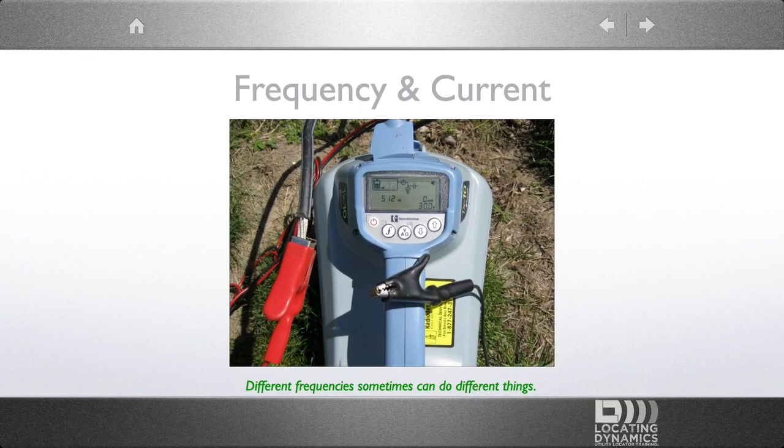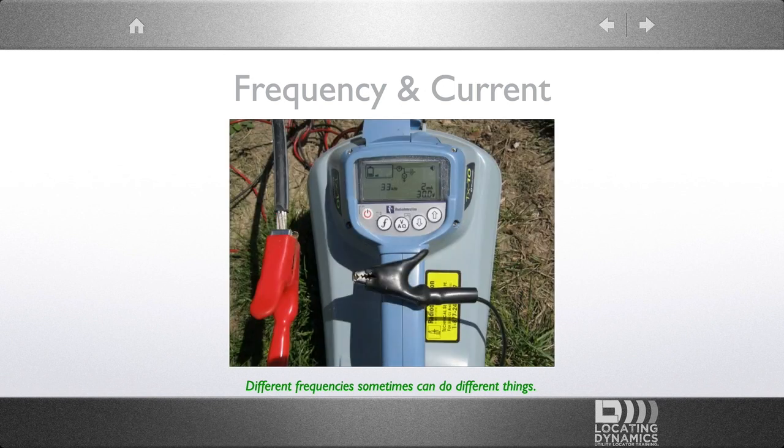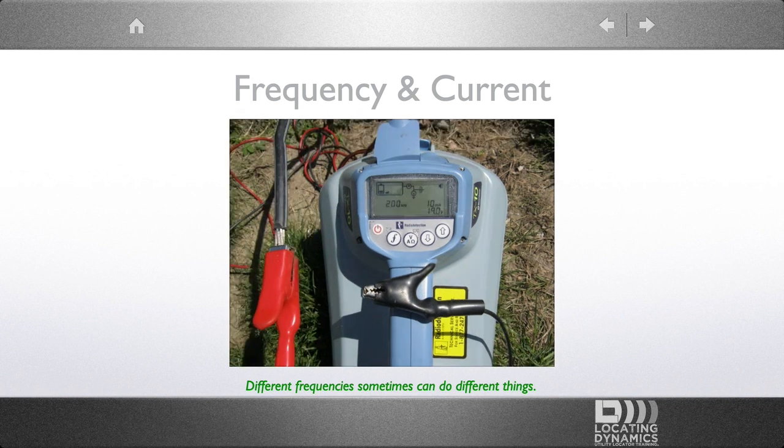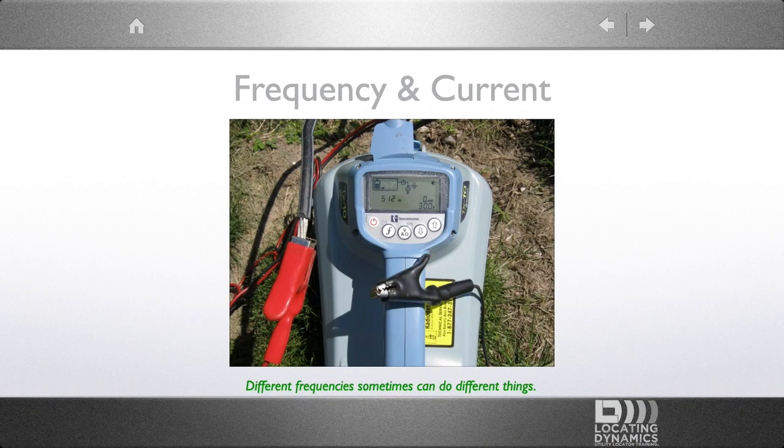In this example, there is no far-end ground on the dummy neutral scenario setup, nor is there a ground on the transmitter. The scenario does not contain a ground in the circuit whatsoever. The reason for that is to showcase how different frequencies can fight resistance better than other frequencies independent of all other factors. On the transmitter, 512 Hz is outputting 0 milliamps.